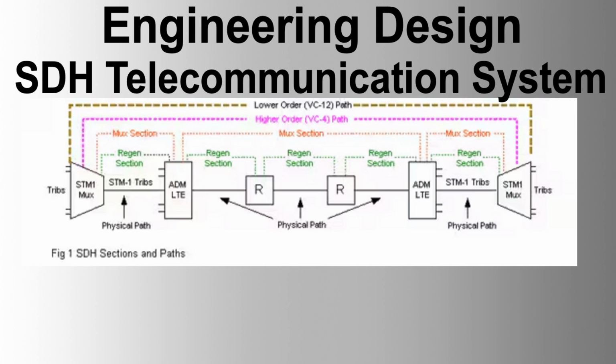The SDH subnetwork connection protocol. Subnetwork protection. The subnetwork connection protection SNCP method employed is critical to establish maximum network availability. Each transmitting signal node shall be permanently connected in both main and protected traffic directions.